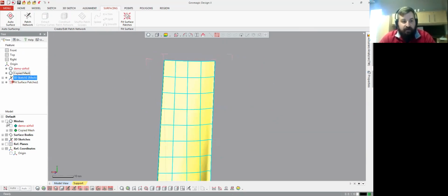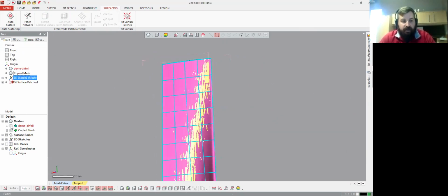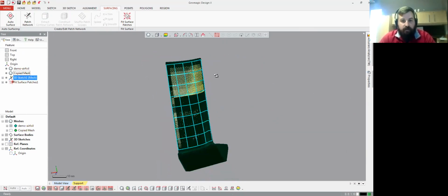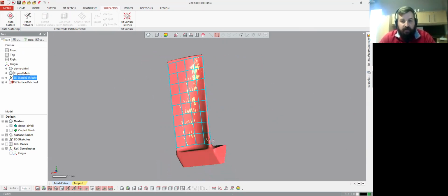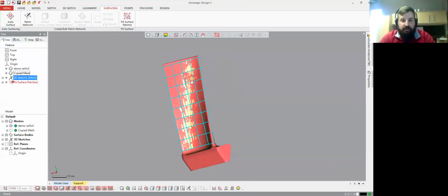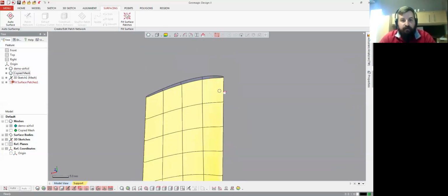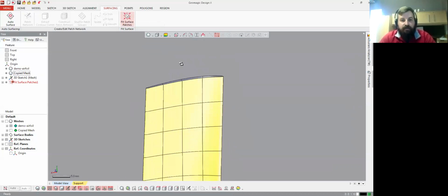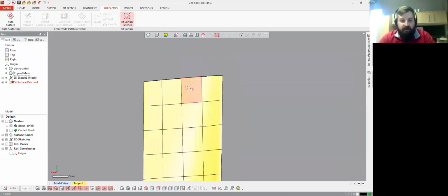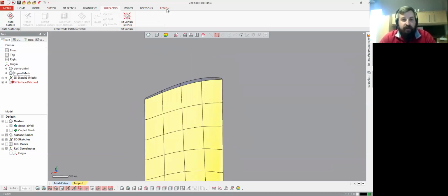So the next thing I want to do, now that I have that blade, is solidify it by extending it and capping off the ends. What that allows us to do is merge it with this body that we're going to create down here using traditional mesh sketches. First thing I'm going to do is extend everything and make sure that we're going past the areas that we need so we can trim those off later.